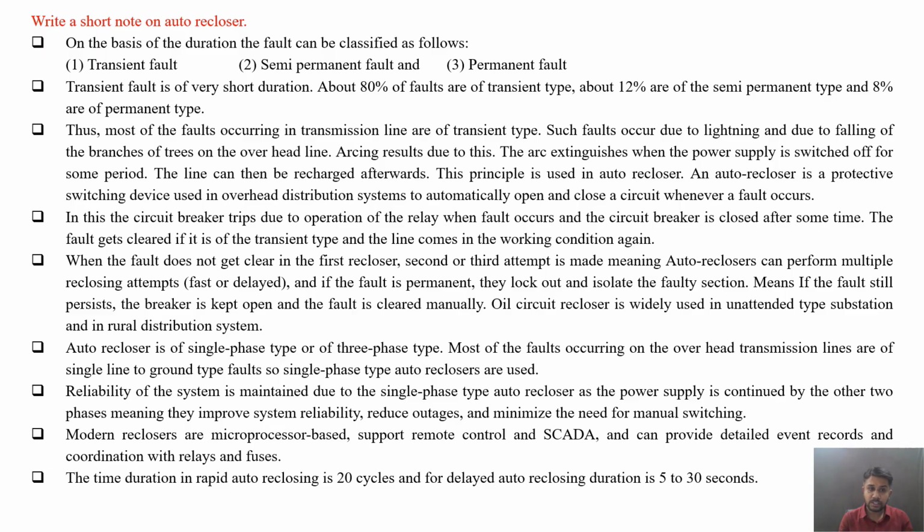The modern reclosures are of microprocessor based. They support remote controlling and SCADA system, that is supervisory control and data acquisition, and can provide detailed event records and coordination with the relays as well as with the fuses. The time duration in rapid auto reclosing is 20 cycles, and for delayed auto reclosing duration is for 5 to 30 seconds. So these are some informative notes on auto reclosure.